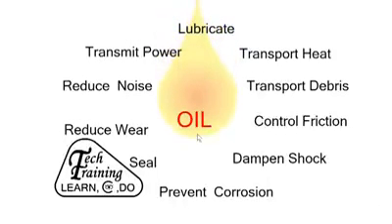As manufacturers strive to improve efficiency and economy, it places a more onerous task on the lubricating system. Engines run at higher temperatures, utilizing the minimum amount of lubrication oil. The characteristics of the oil are improved with additives which inhibit corrosion, reduce foaming, reduce oxidation, and act as a detergent.